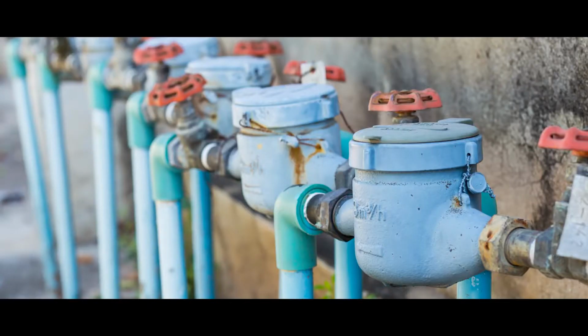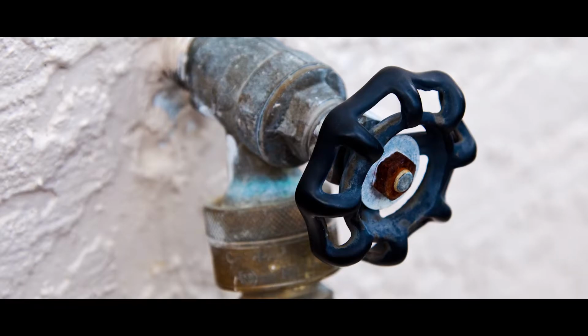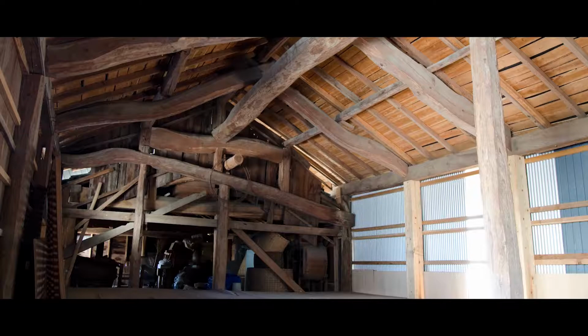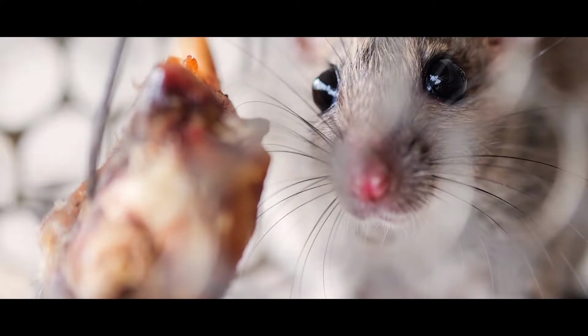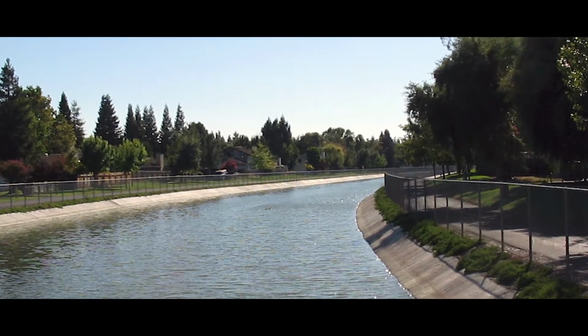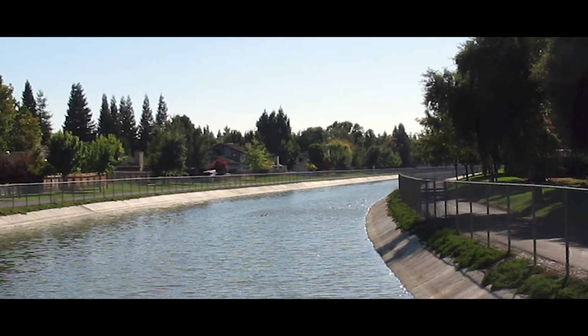Irrigation systems should include check valves, anti-siphon devices, or other backflow prevention systems to prevent chemicals injected into the system from flowing back into the well, back into surface water, or onto discharge land. Unused irrigation equipment should be stored in a clean environment that is free of pests. Areas beyond your property may cause problems also, so it's important to check that land too. For example, if you use surface water from a stream or canal, look upstream for potential concerns.